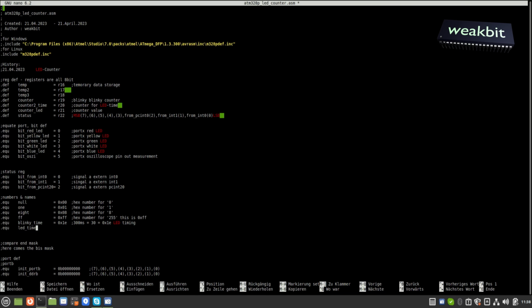What did we say? We have 10 milliseconds per cycle, we take 100 milliseconds, for example, this means 0x0A. This is 10 times 10, 100 milliseconds, and it's 0x0A. This is the LED counter, LED counter timing.